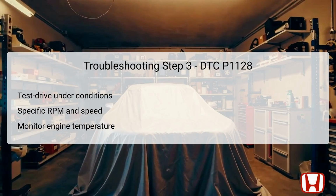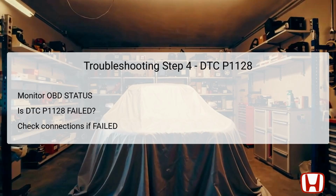These conditions allow the ECM to evaluate proper engine performance. Following these parameters is crucial for ensuring accurate testing results and helps the technician understand if the DTC persists. After completing the test drive, monitor the OBD (onboard diagnostics) status for DTC P1128 using the HDS. You should look for the status in the DTCs menu.